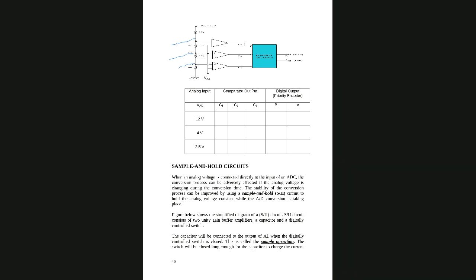You can apply the voltage divider rule, or this method is very simple, because all of the resistors are equal. So we have 7.5 plus 3.75, so we have 11.25, right?